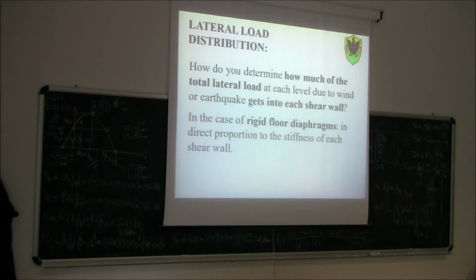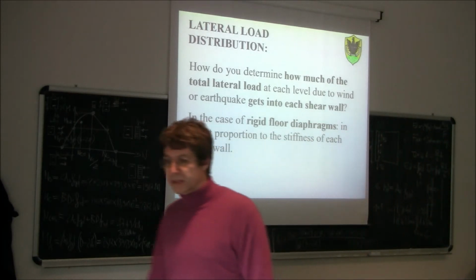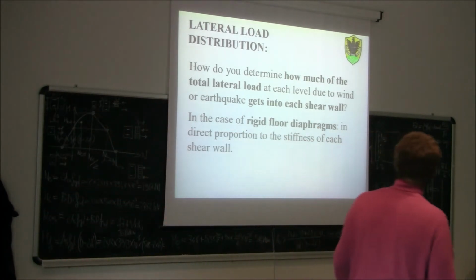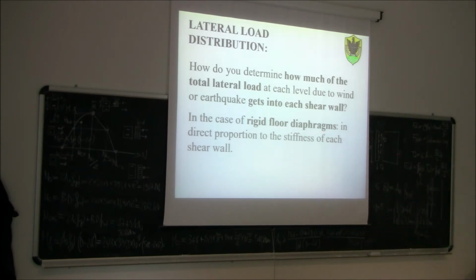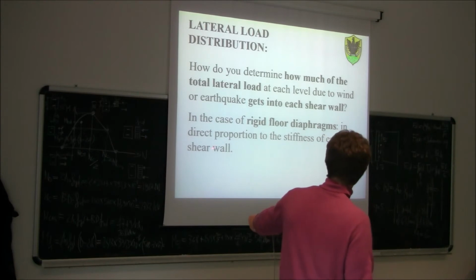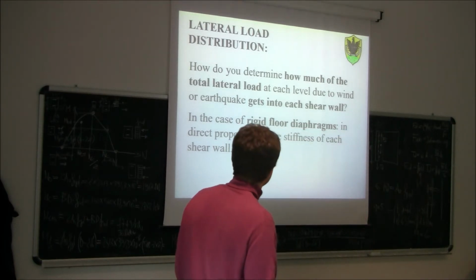So, another important thing I want to share with you is this: in reinforced concrete design, you made an important simplification, which is actually true for a reinforced concrete floor. You assumed that the floor was in-plane rigid in order to then calculate the distribution of forces. Now, is it true that for a timber multi-story building the floor can be regarded as in-plane rigid? Because of course, if the floor is in-plane rigid, the distribution is in direct proportion to the stiffness of the shear walls, this for sure holds.